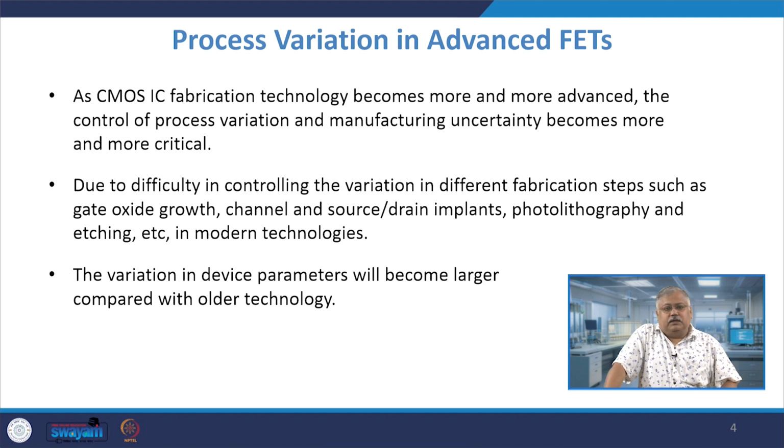Now, the problem is the process variation especially can be of two types. One is of course the process variation of the device dimensions and also of the doping of the device. So, you wanted to have a device dimension of say 2 nanometer, but when you actually did a lithographic step and you did an active layer deposition, you saw that it becomes 2.5 nanometer or 2.2 nanometer.